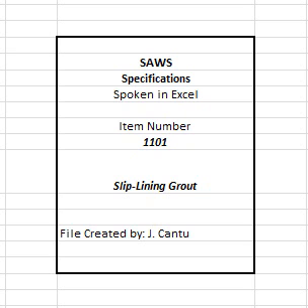3. No deleterious amounts of toxic or other poisonous substances shall be included in the grout mix nor otherwise injected underground. 4. Final cleanup. No hardened grout is permitted in the slip liner pipe invert after completion of grouting operations. 5. Dewatering system operation. Operate dewatering systems until the grouting of slip liner pipe is complete. 6. Testing. Test grout equipment and procedures in accordance with approved submittals.